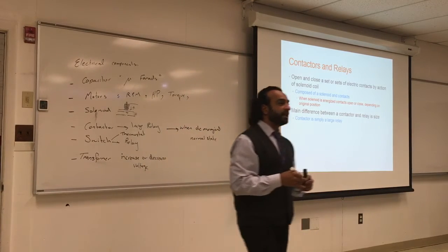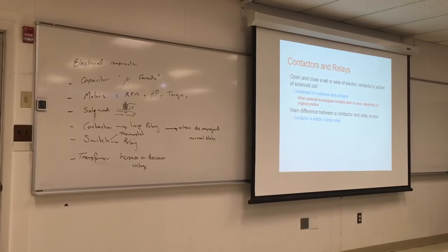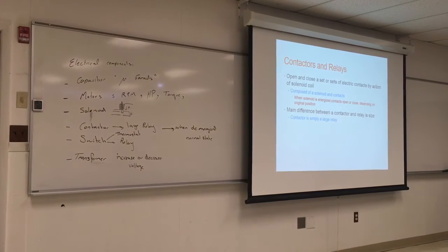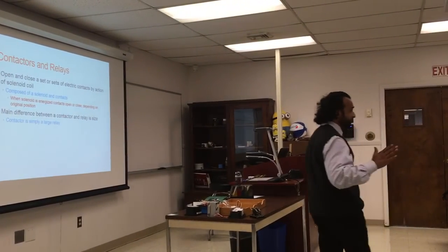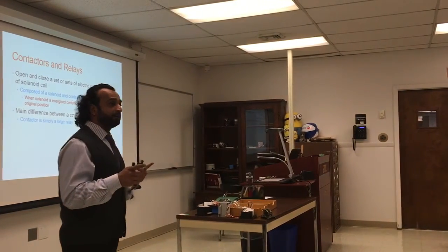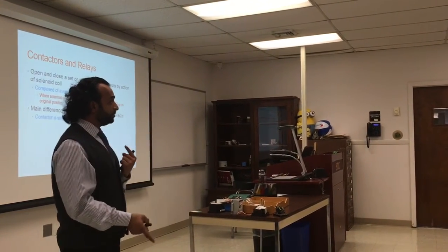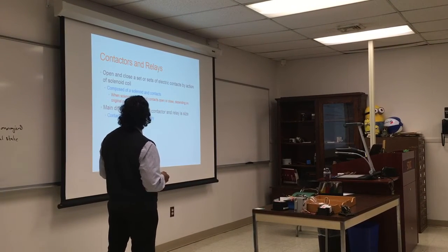So some relays are normally closed or normally open. What do we mean by that? When we de-energize it, when we cut the power, it will go to its default state. It's either closed or open. Please try to remember that. And some of the contacts will switch or reverse based on the state. So normally closed, normally open.